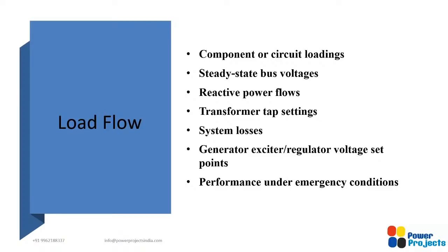Load flow analysis also helps to find out the losses in each and every branch, like transformers, transmission lines, etc. And of course, it also gives the total losses in the system. This also provides additional information: what's the optimal configuration in which you need to run your system so that the losses are minimal. So let me repeat my statement. Load flow analysis is going to help you identify the total losses in the system, as well as the individual equipment losses. It also helps you identify the optimal configuration in which to operate your system so that the losses will be minimal. So that's where your load flow helps further.